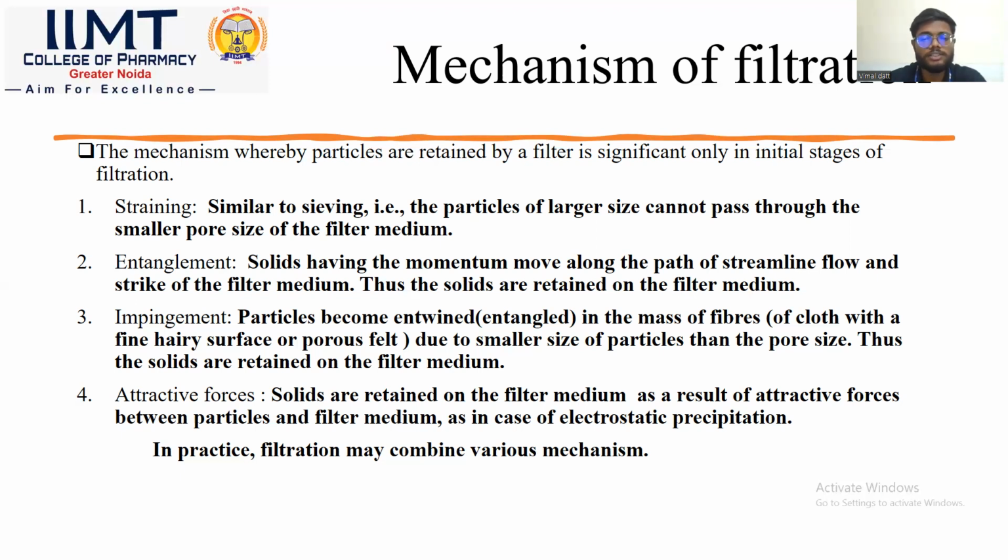Porous felt. Due to the smaller size of the particle than the pore size, the solids are retained on the filter medium. The last mechanism is attractive forces. Solids are retained on the filter medium as a result of attractive forces between particles and filter medium, as in the case of electrostatic precipitation. In practice, filtration may combine various mechanisms.